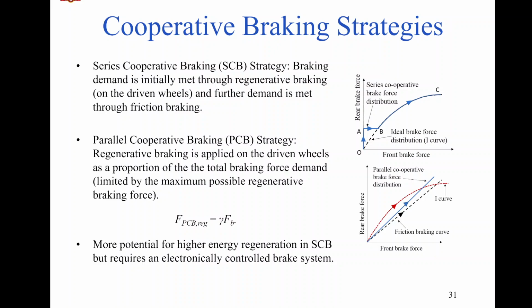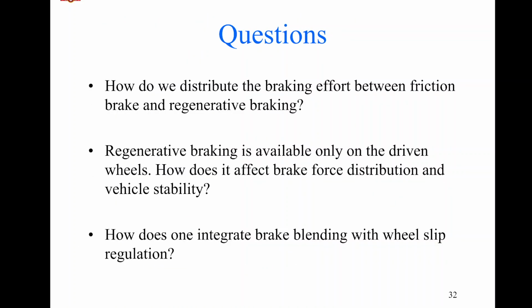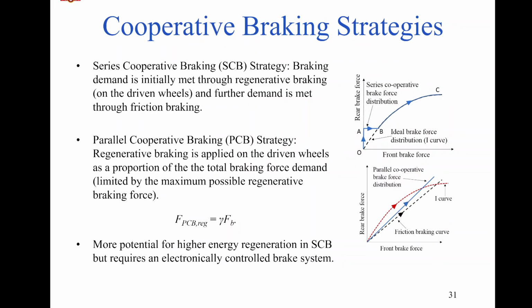So see, regenerative braking in your electric vehicle will help you recover some energy that will go into the battery. If the energy is going into the battery, then it would help you increase your range, correct? So if your demanded deceleration is not too much, that is, if you have not pressed your brake pedal a lot, and your vehicle speed happens to be high enough, the brake system would ask: can I fulfill your demand completely using regenerative braking?